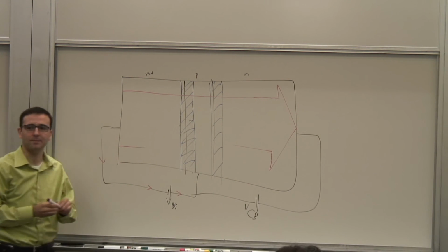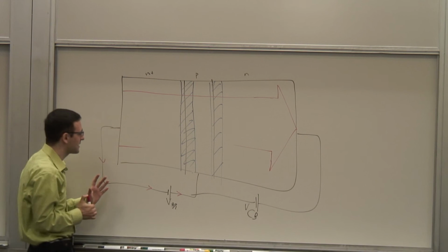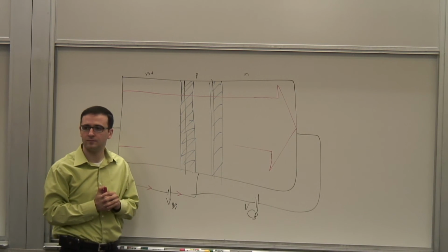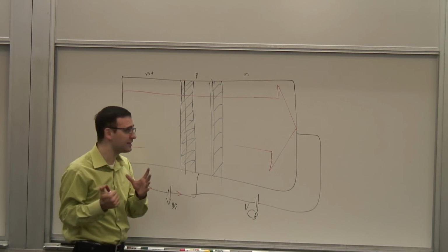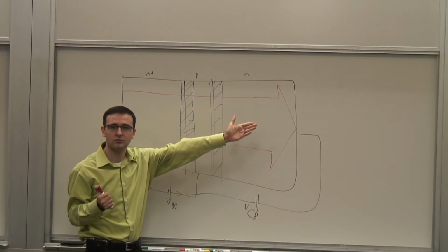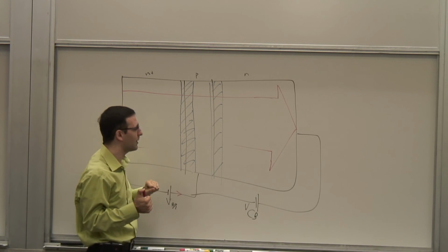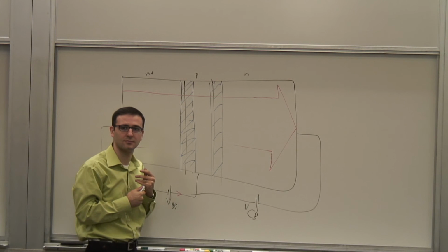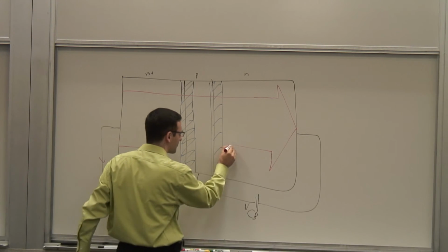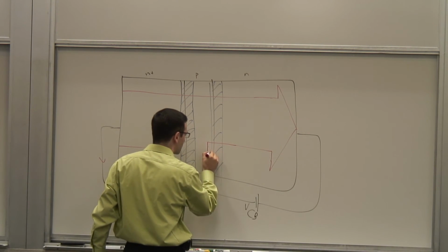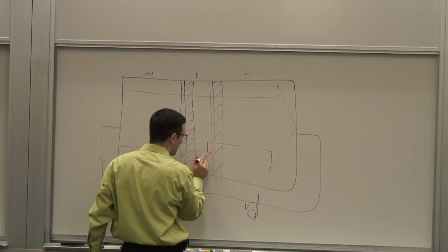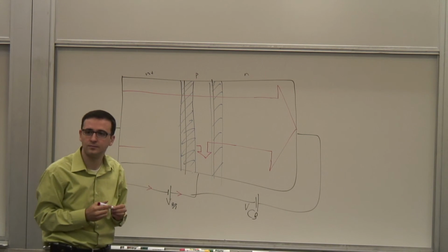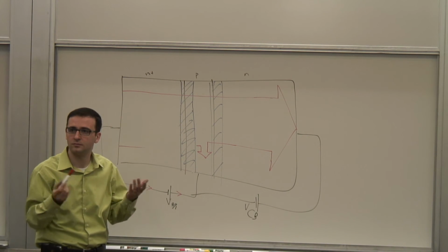Now, what happens with them? Let's follow them. Let's see what happens. Where do they go? What are they spent on? Well, if the transistor is properly designed, most of them make it to the collector. Those are the successful ones. Good. But how about the unlucky ones? The ones that get caught? Recombine. Okay, so a part of that electron flow goes into the base and gets recombined with what? What does it get recombined with?